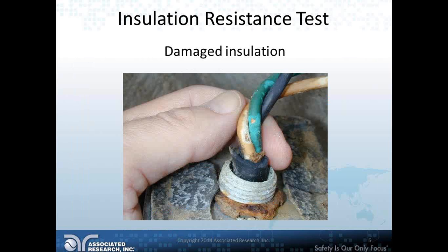Okay, here's a quick example of insulation. I know we've been talking about insulation. Here's a quick example showing us a simple example of insulation on a bunch of different wires, and you can see over time the insulation has deteriorated, and you can see exposed conductors. Similarly, inside an electrical product, the insulation can go bad over time. So that's where the insulation resistance test comes in.